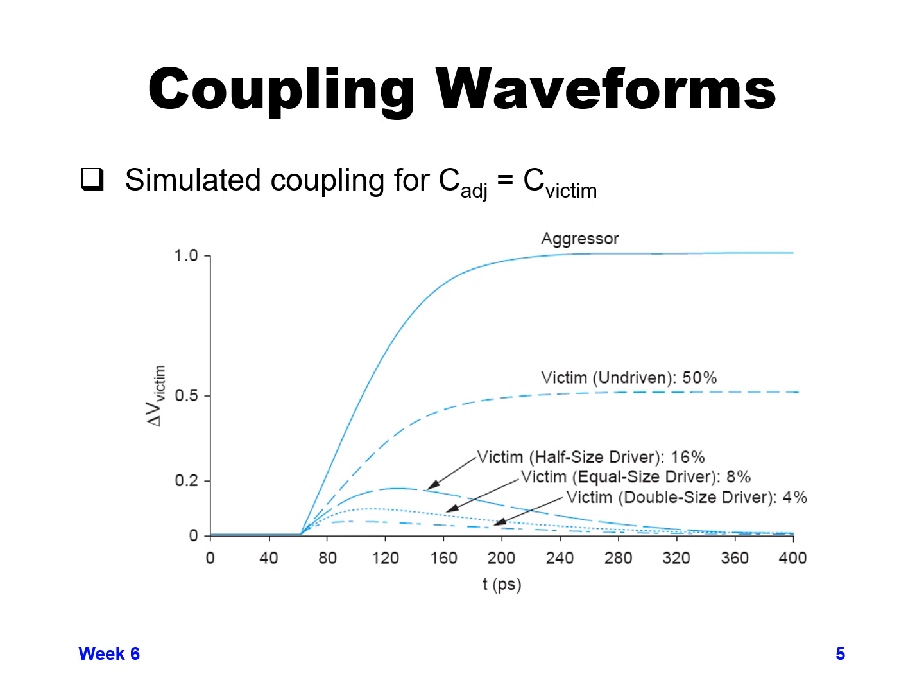But keep in mind this noise can have somewhat of an additive effect if we have multiple wires. So let's say you have a wire on either side of a given victim and both of those wires are going at the same time.